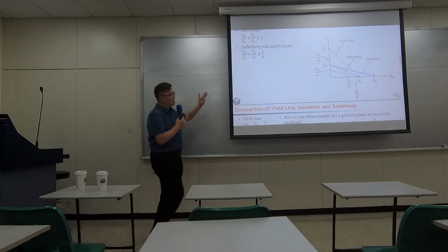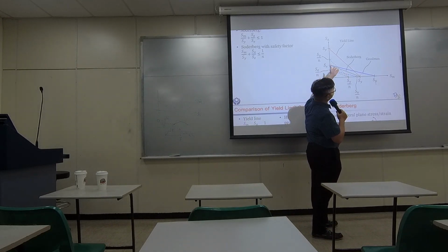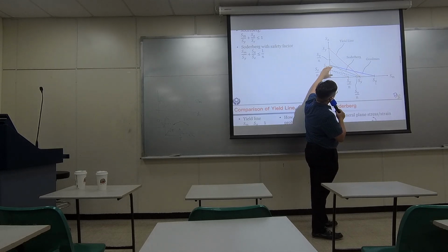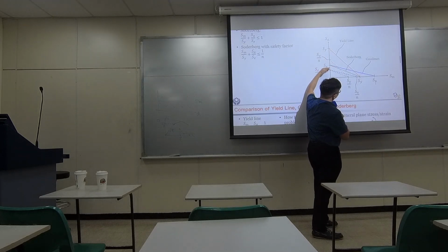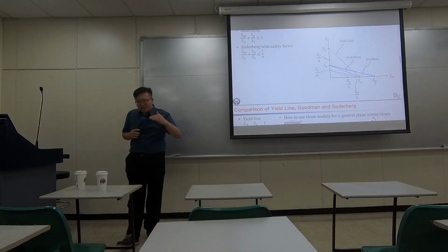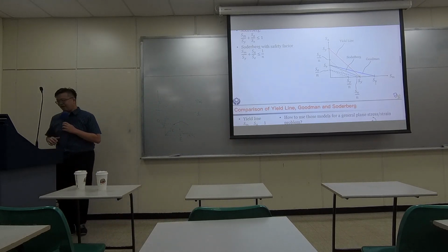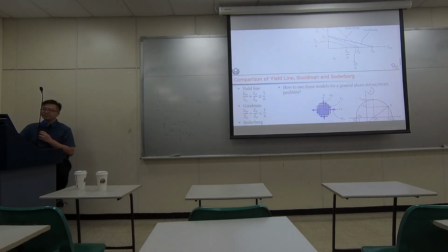Okay, so that's why the design boundary looks like this. They believe due to fatigue and after a certain amount of cycles, the strength drops to a lower level. So we should use this lower value as our design upper bound. Okay?